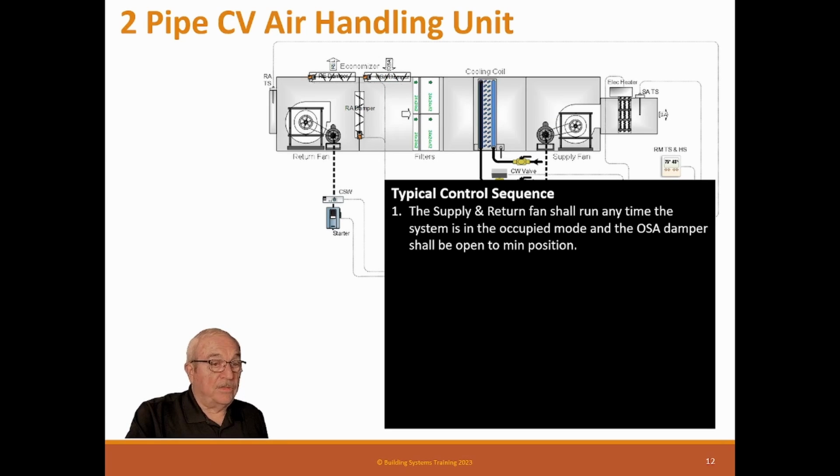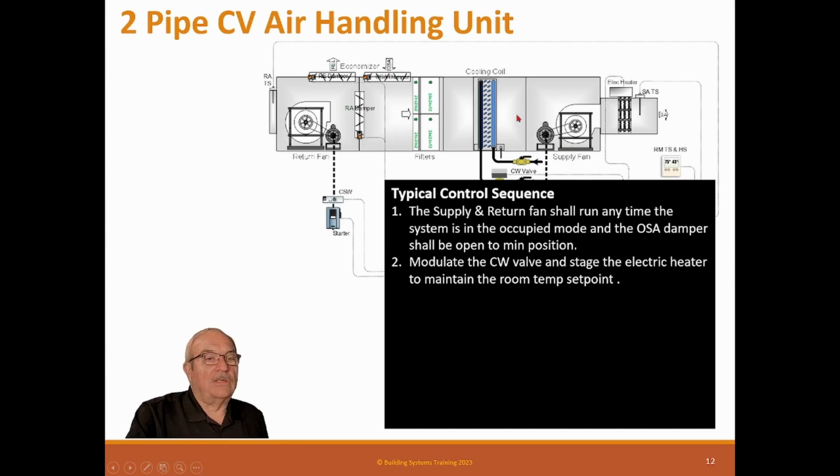I'm serious. If it's a 5-foot long, 3-foot wide louver automatic damper, it leaks quite a bit, actually, because they call them low leak dampers, but that's in comparison to a damper you can almost see through. So low leak is not that low, so you still have to look at that.